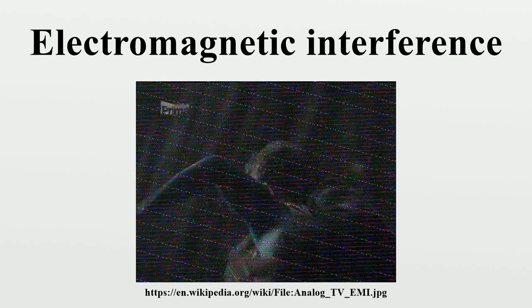RF immunity and testing. Any unshielded semiconductor will tend to act as a detector for those radio signals commonly found in the domestic environment. Such a detector can demodulate the high-frequency cell phone carrier and produce low-frequency demodulated signals. This demodulation manifests itself as unwanted audible buzz in audio appliances such as microphone amplifiers, speaker amplifiers, car radios, telephones, etc. Adding onboard EMC filters or special layout techniques can help in bypassing EMI or improving RF immunity.